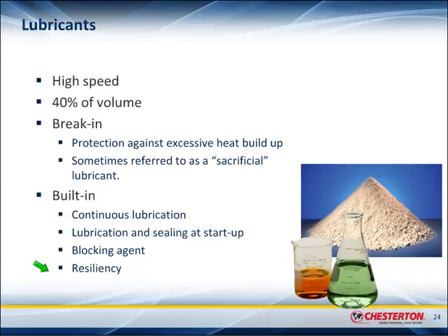Is it possible to have a break-in and built-in lubricant? Yes. Most packings have a built-in lubricant and a break-in lubricant. And break-in lubricants are specifically used for dynamic applications. In valve packing in general, you don't need lubricants. What you need is blocking agents. So specifically for pump packings, you see these break-in lubricants.